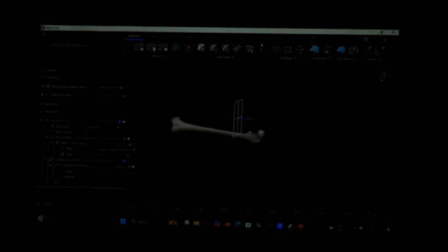See, your plane is here now. You can change the view. Your plane is here. I will drag this to our required place. Here I want to drag, and this position you don't need because a reference plane is infinite geometry. That is like a reference geometry that doesn't have dimensions.